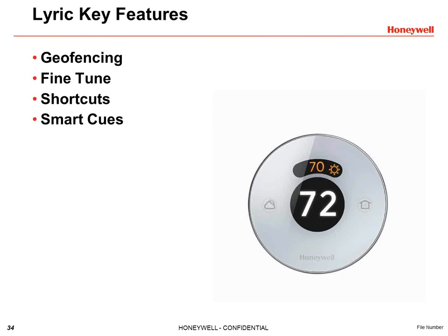And when those cell phones leave, and there's different settings, but I think the average is about 500 meters, so you leave, you go down the block, and it knows to go into setback. So you're not programming this thermostat. It knows when you leave and automatically goes into a setback status.